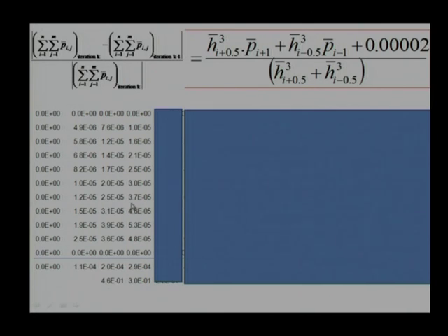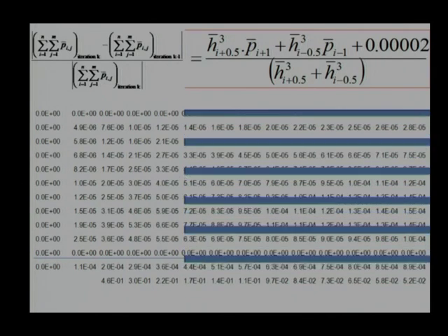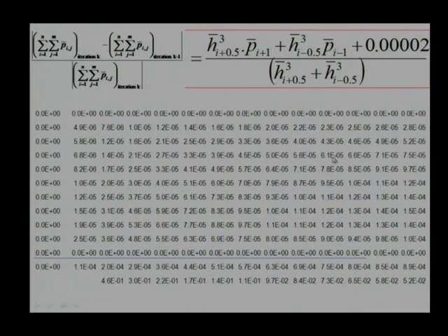That means we are going towards the convergence side. That indicates that in every iteration this convergence value is decreasing. That indicates clearly that we are moving in the right direction, the solution is stable, and we are going to get a solution maybe after a number of iterations. That depends on which kind of scheme we are using. After an additional iteration, this epsilon value is turning out to be 0.22, which is better than 0.3. That is why we prefer this convergence.